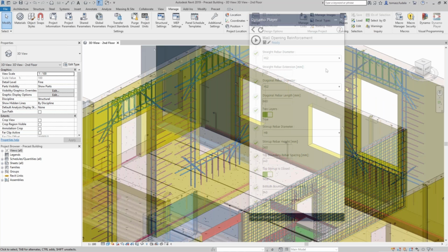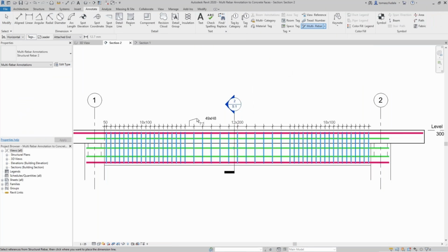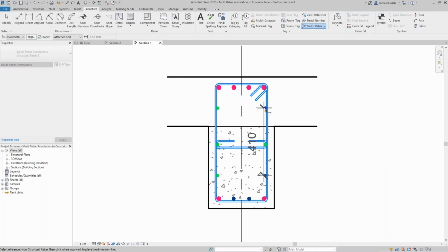You can see here I'm taking the edge of that beam as a last reference. So here in this example again, I draw a line, I take the reinforcement and the edge of the slab. All I need is an edge as well as a reinforcement, and it will work for me. Now it gives me the rebar annotations directly.